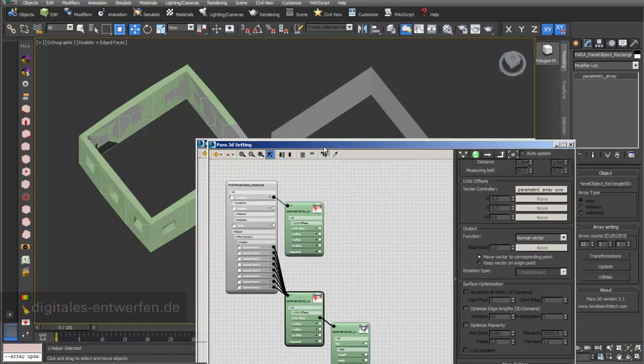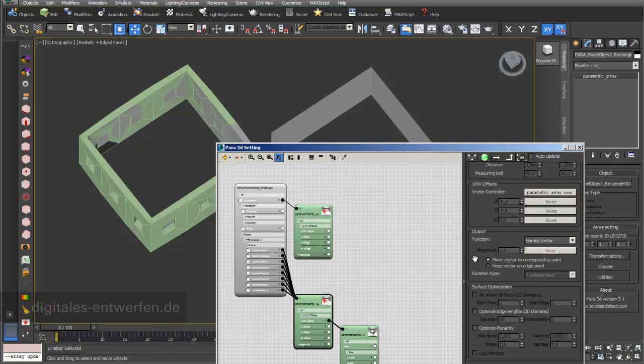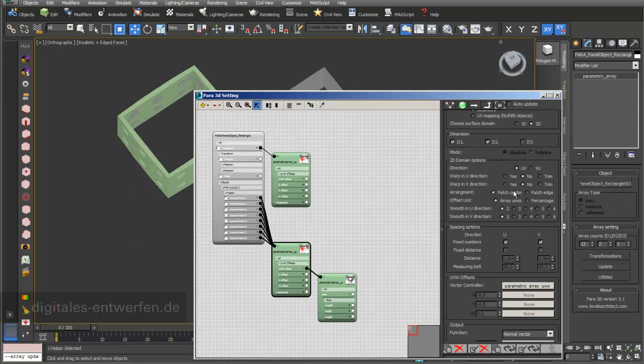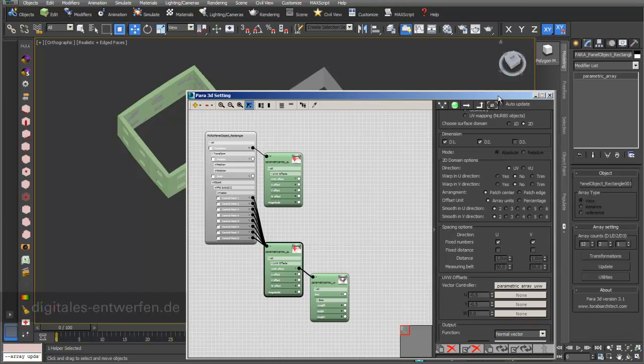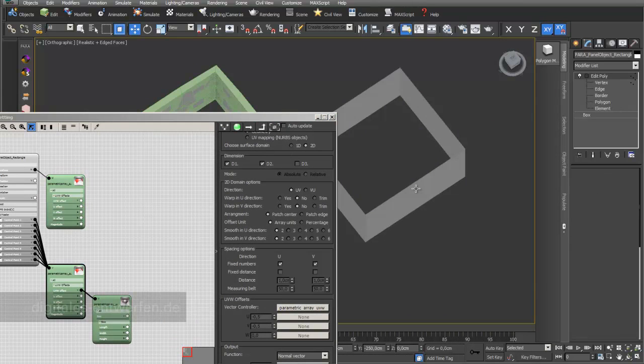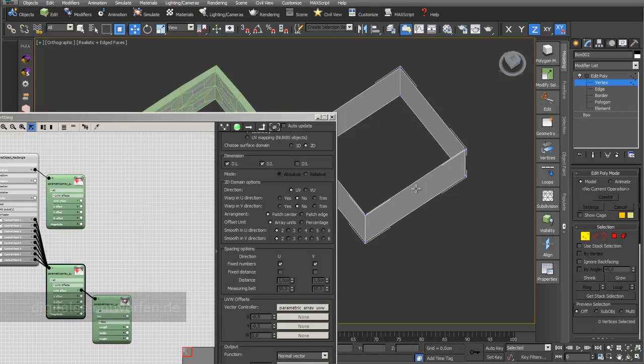Okay, I go again into 12, and what we wanted to look at is these kind of settings. 2, 3, 4, 5, 6 in U and V direction stands for the amount of vertices Planarity uses for smoothing, meaning it produces interpolated curves between these kind of vertices.